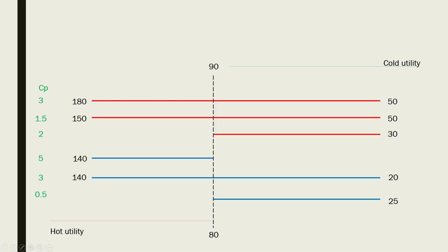At the end of the heat exchanger network, we want the section above the pinch to use only hot utility. So we need to provide the hot streams with the cooling loads needed so they can achieve the desired temperature. And we can use the hot utility to give extra heat load for cold streams if needed. Remember that when you design a heat exchanger network, always start from the pinch and move outward. Let's start by calculating the heat exchanger network in the above the pinch section.